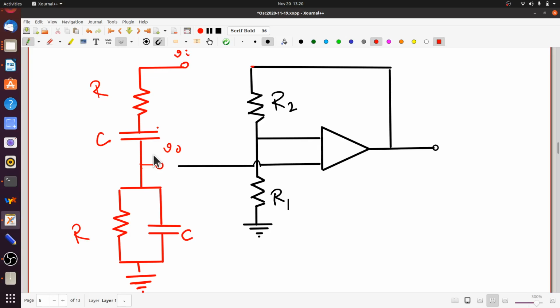Just to remind you, you put two impedances in series and they are grossly mismatched, the series combination essentially looks like the bigger impedance. And if you are talking about a parallel combination, the parallel combination looks like the smaller of the two impedances. That's exactly what we are using here. At low frequencies, C has a much higher impedance. So the series piece up here behaves like C, and this part behaves like R. So this is like a CR circuit whose output leads the input.